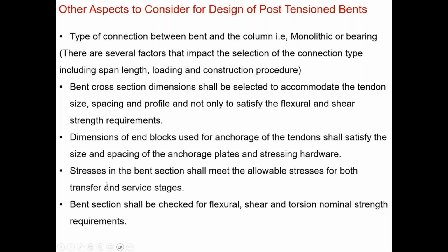And of course, that's what we normally do in design for any pre-stressed member, pre-tensioned or post-tensioned, that you want to make sure the stresses in the bent meet the allowable stresses at all stages, including transfer and service, and also that the bent section has a sufficient nominal capacity for flexure, shear, and torsion, and all other requirements.